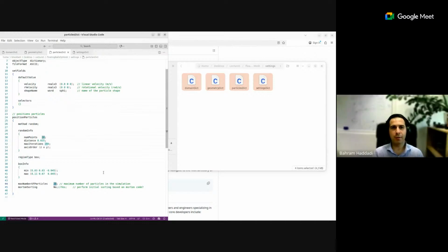That's a very nice and valuable point. So please don't forget it. It's about the central particles. And as Hamid said, if you make this mistake, it might be that you're pushing the particle into the wall, and as soon as you start the simulation, it will be shot somewhere and cause some instabilities in the simulation, even diverging. Good. And so far we created the geometry for our DEM side.